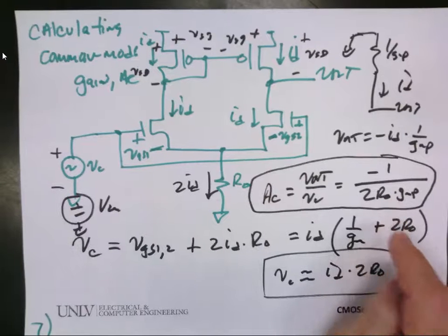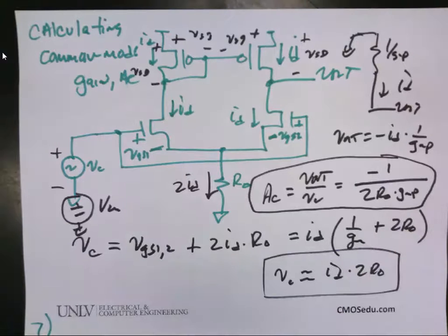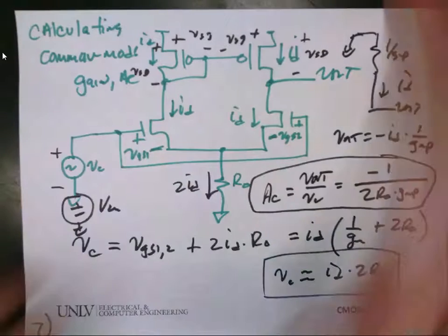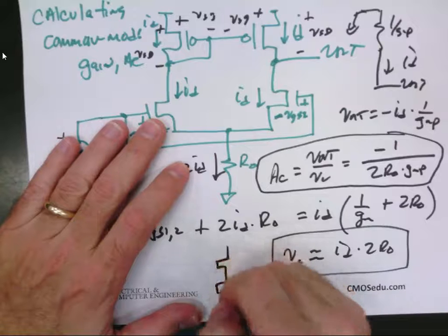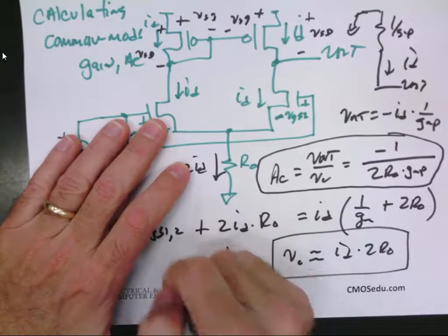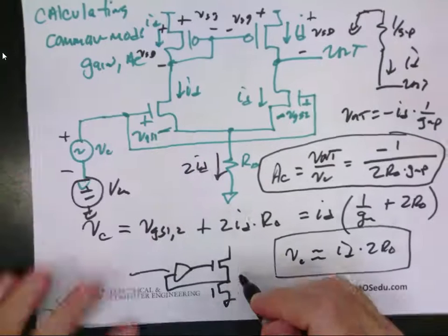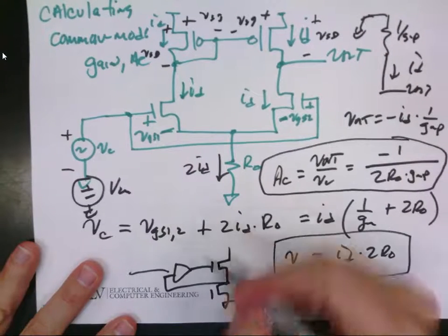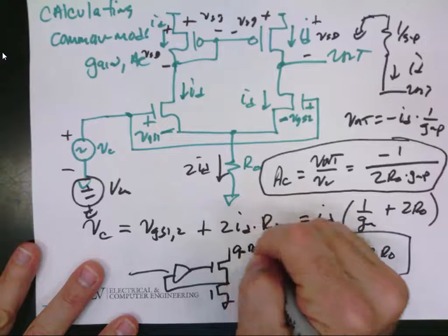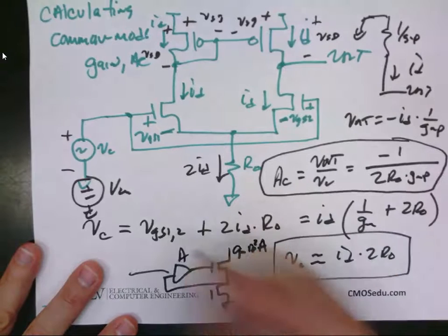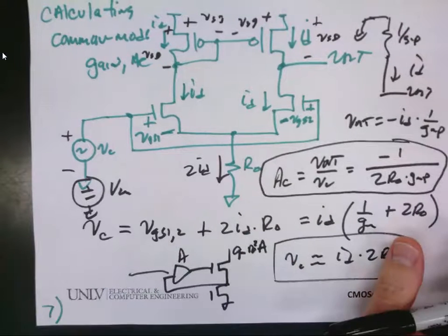So let's say I used a regulated drain. What does regulated drain mean again? Remember, it's one of those sources that does this, where you have that extra bias and then it acts to hold this node, so then the output resistance becomes GM R out squared times the gain of the amplifier, so it shoots up to a super high value.